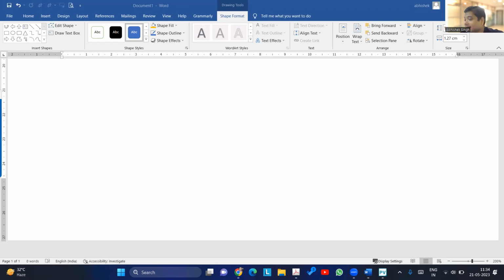See, the reason for not using it at low temperature is the problem of brittleness. The material becomes brittle, and we don't want to use a brittle material because the failure will be catastrophic. That is the simple reason. Now, at what temperature I can use it will depend upon whether that material is brittle or still ductile.